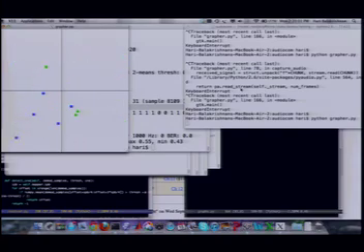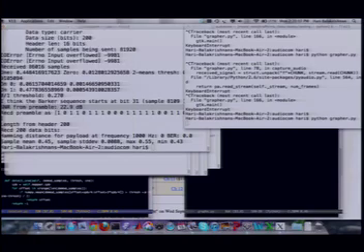So the question is, how does the receiver know that what it's receiving is part of a legitimate transmission? All communication systems need to solve this problem of synchronizing between the sender and receiver, and that's done using a preamble. The preamble is nothing more than a well-known sequence of bits that the sender and receiver both agree on. So in this case, our preamble is that long sequence there, 1, 0, 1, 1, 0, 1, 1, 1, etc. And there's some guidelines and rules of thumb that go into what makes a preamble good and what makes it not so good. We're not going to worry about that here. I'm just telling you that's the preamble.